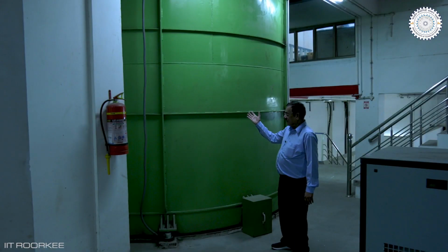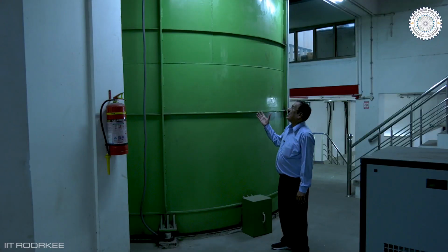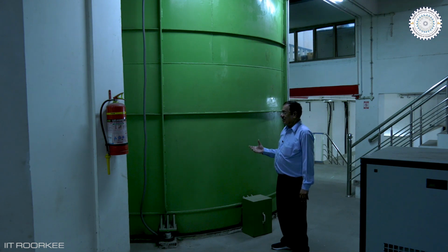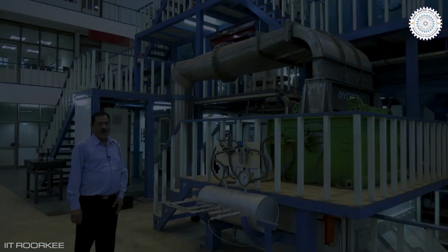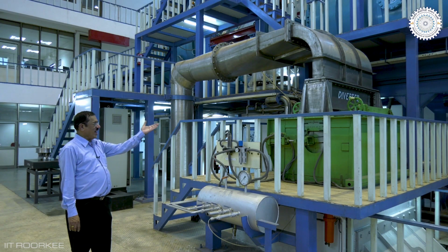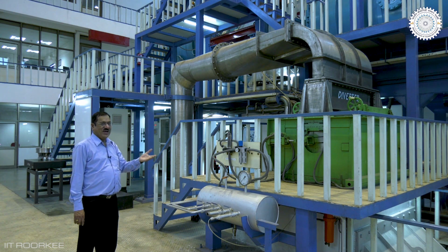This is a measuring weight tank which is mounted on 3 load cells, 22 tons each. The capacity of this tank is 45 tons of water. This is used for flow calibration. We know the weight collected, the mass of the water collected in kg, and the time, so we know the actual flow. Here we can see the flow diverter which is used for diversion of water to the main measuring tank during the flow calibration.